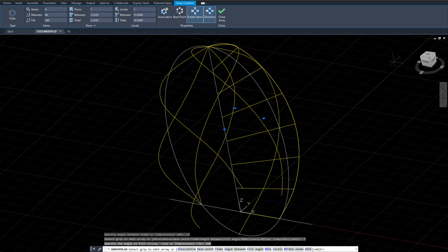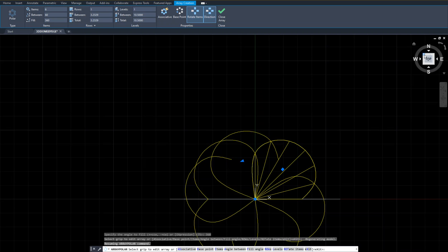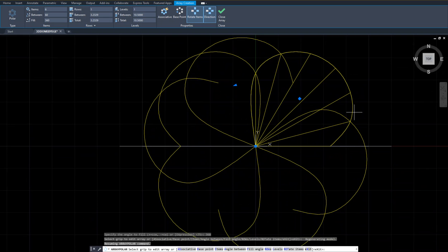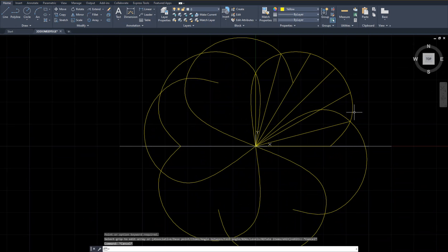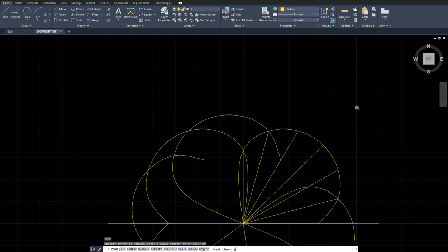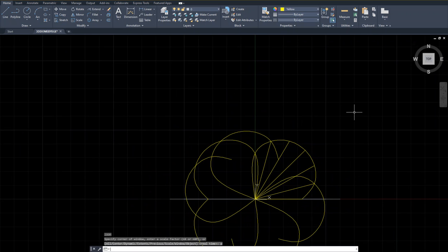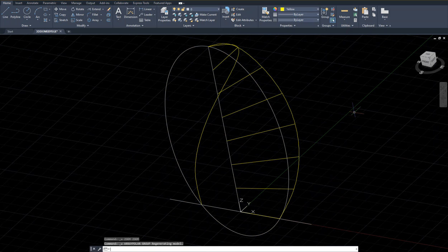Also look at it from the top, what it looks like. So it's going to look like that. And Z enter, P enter takes you back to it. Escape and Z enter, P enter. This may be good, but honestly, you may prefer more than that. Maybe 12 of them. So go with that.